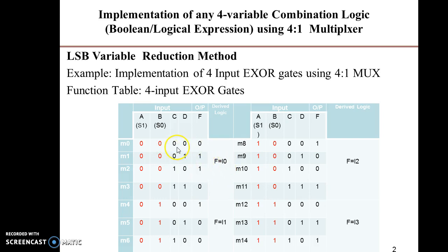So this is nothing but, if I compare the C, D and F variables, the function I can observe over here is nothing but XOR. So here the I0 data input pin I am going to connect to C XOR D.